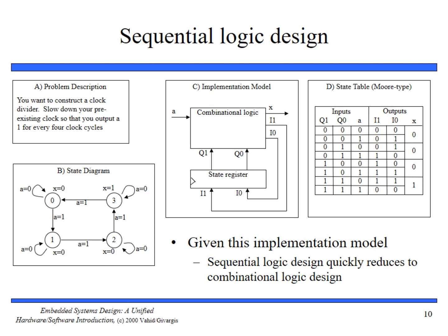For this we need a state diagram. This is our state diagram. This A is our input, X is output, and these Q0, Q1 are input states, and I0 and I1 are output states. Why do we have Q0 and Q1, 2 bits? Because you can see 1, 2, 3 and 4 states: 0 0, 0 1, 1 0 and 1 1. These are our 4 states.